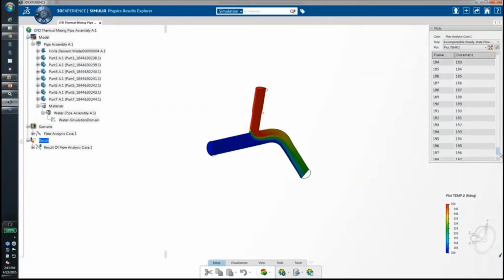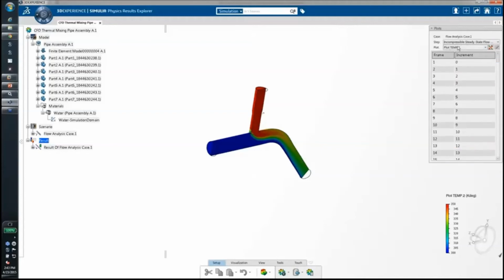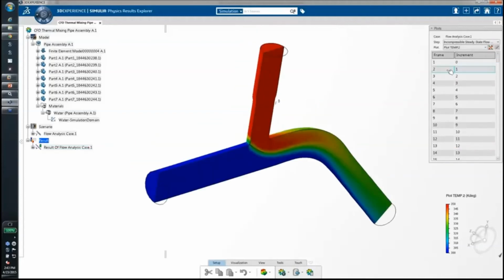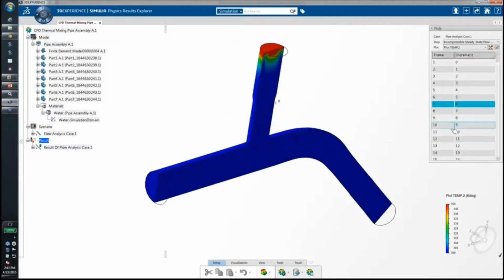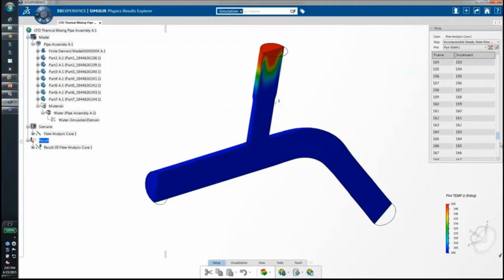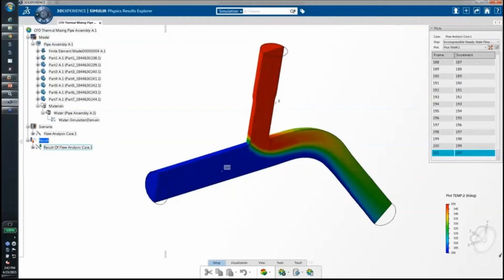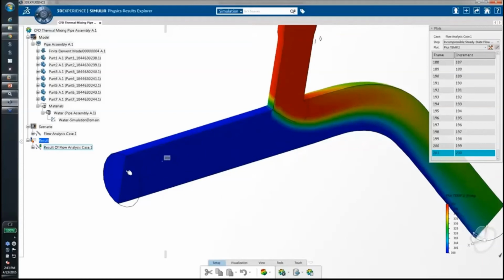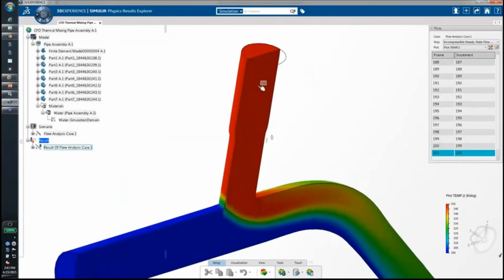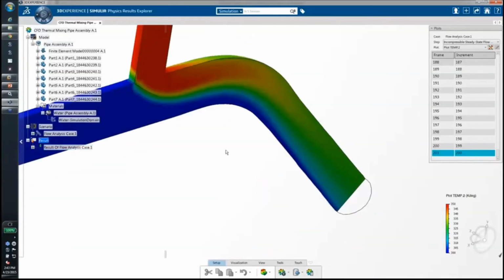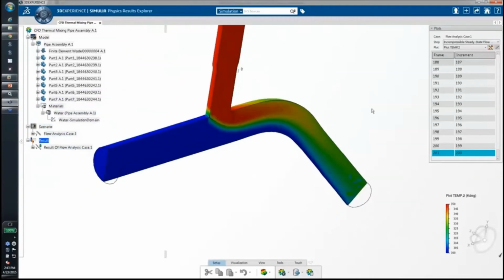So you see we set up 200 increments, or I guess I did 200 increments. These are the different increments here. This is a temperature plot. I've got it sectioned. So these would be the increments as it progressed, right? If I go to the end, when I'm achieving steady state, then we have the different temperatures across that section. You can see, remember, we came in at 300. I guess on this simulation I set it up at 350, and then we had that mixing. It's coming out at, probing at, 324, okay?